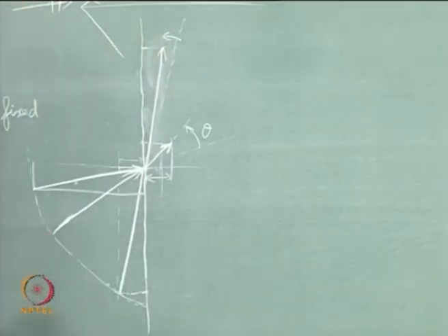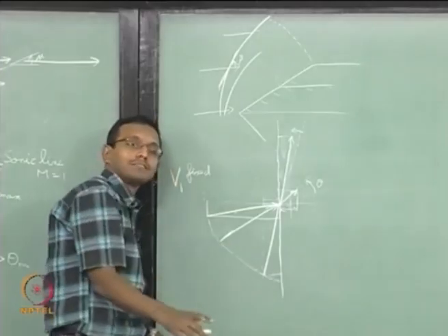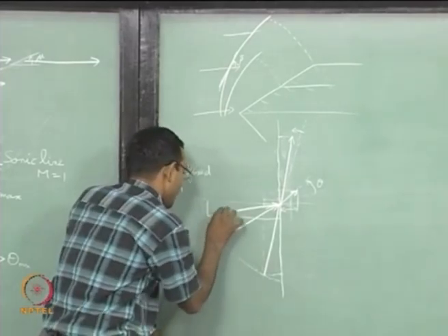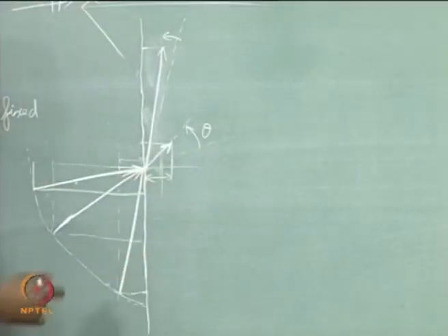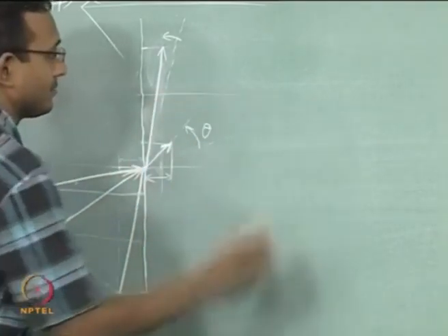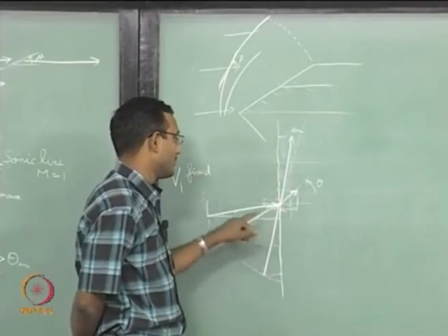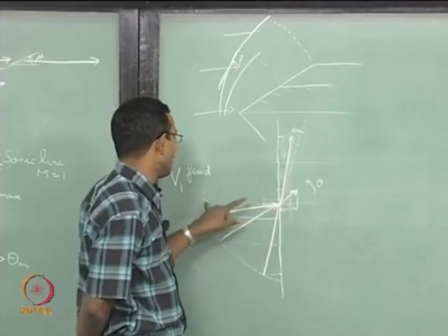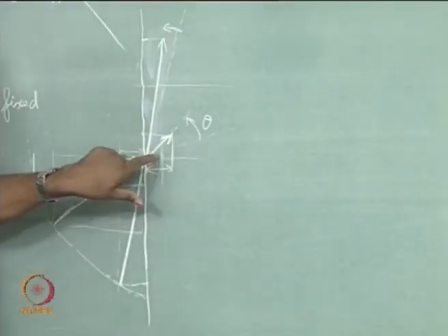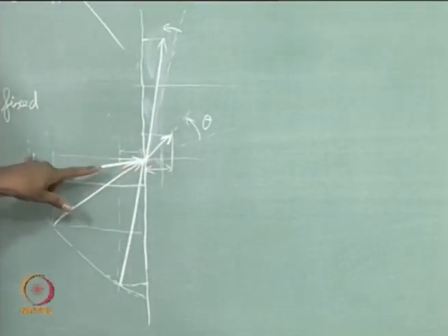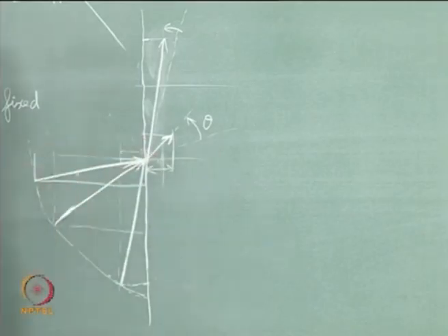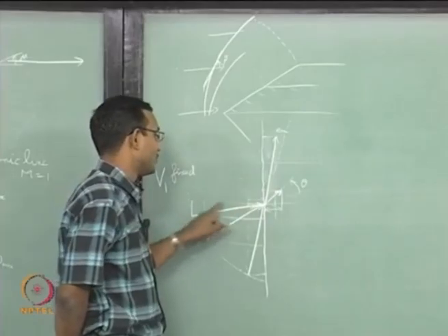Now, we will go to the next case. The next case is something in between, and I am assuming this is going to be close to your theta max somewhere, I do not know where exactly. So, I will draw the normal and the tangential on this. The tangential has the same length, that will be here, this line. Now, I have to look at the shock strength, it is going to be some u2 by u1 in between this case and this case. Here the u2 by u1 we said was roughly half, in the other case the full amount is covered in 1, 2, 3, 4, so 1/4. So, let us pick 1/3 for this case, u2 by u1 is 1/3.